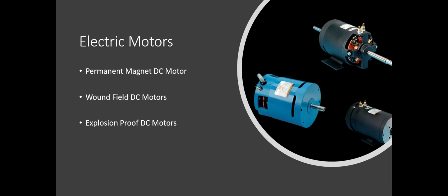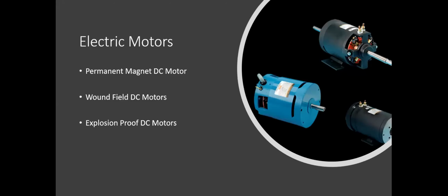And finally, for hazardous locations that may have flammable gases or liquids, we've got the explosion-proof DC motors. These motors are typically a sealed design that is intended to contain an explosion should it occur within the motor. The design also prevents the release of explosive gases or vapors into a working environment. And further enhancing the safety of these units, the motor's brush and commutator assemblies are separately sealed in the event that arcing might occur. And this prevents igniting any dust or vapors in the air.